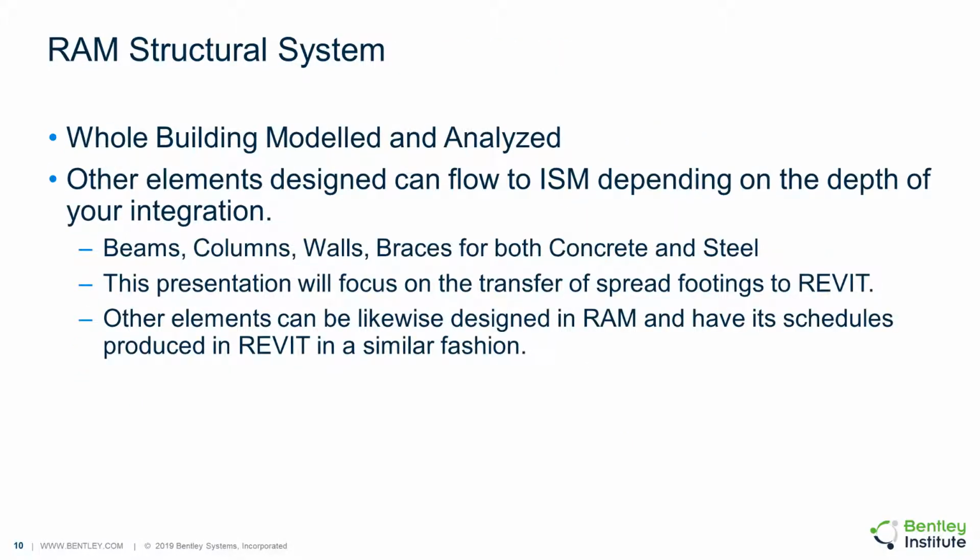Okay, first off, we need a building model in RAM structural systems. You can either do that from scratch or similarly use ISM to bring that model in from Bentley's other modeling applications or even Revit, via ISM. So once we have a building model in RAM structural system, we analyze and have that designed as well. We can have many aspects of the building elements designed for us: concrete columns, beams, walls, and foundations, which is the subject of this talk.